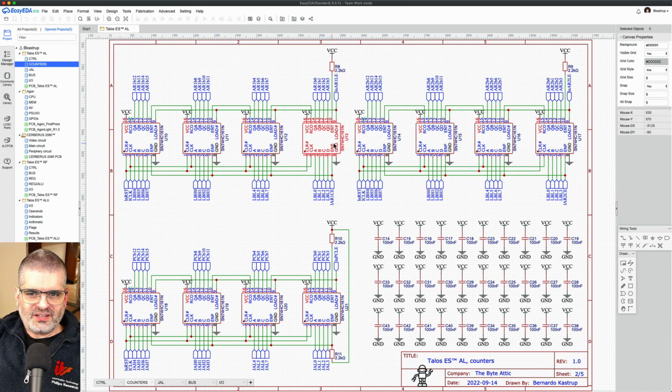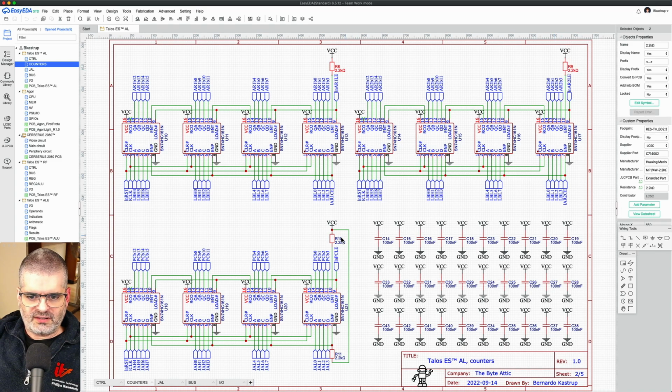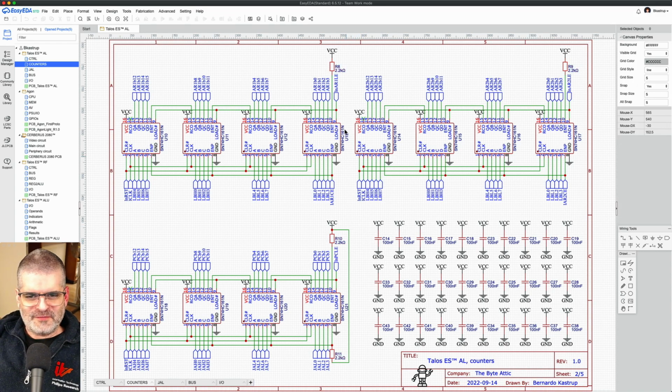This is not the case here, so why am I doing this? Well, it's good design practice, and worst case scenario, it serves as a current limiting series resistor in case something goes wrong with the chip, the chances of which are practically 0. But resistors cost nothing and they're very easy to place and route. So just good design, hygiene, and practice. I just put them in there.